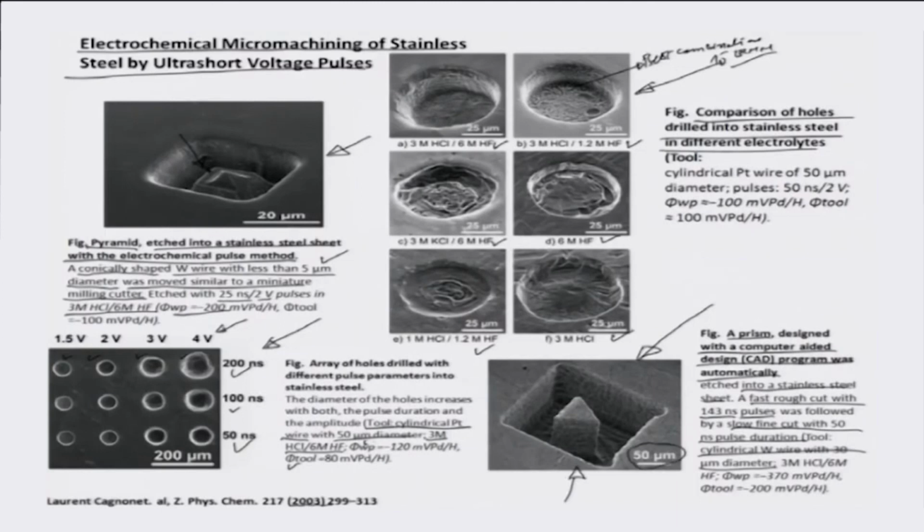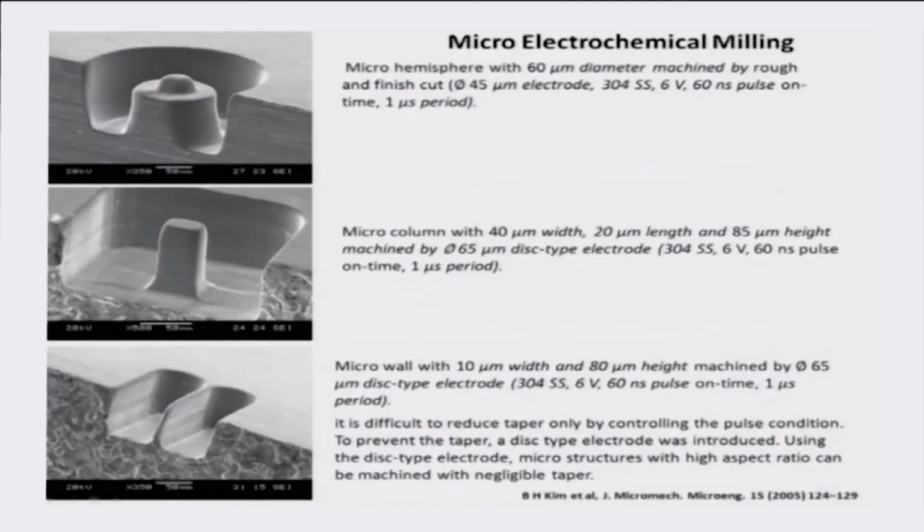You can look at the scale here, it is about 50 microns, meaning thereby that this one side alone is close to about 50 microns, and the whole width here is about 100 by 100 microns, and the depth cannot be figured out here in the SEM, but it is actually about 100 microns or so. So, getting such a feature using non-lithography, non-energy beam techniques is highly cumbersome unless you go for electrochemical micromachining. So, there are some beautiful illustrations of electrochemical milling here.